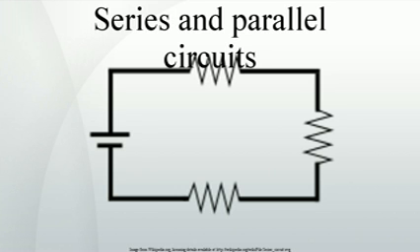Parallel circuits. If two or more components are connected in parallel, they have the same potential difference, voltage, across their ends. The potential differences across the components are the same in magnitude, and they also have identical polarities. The same voltage is applicable to all circuit components connected in parallel. The total current is the sum of the currents through the individual components, in accordance with Kirchhoff's current law. Voltage. In a parallel circuit, the voltage is the same for all elements.